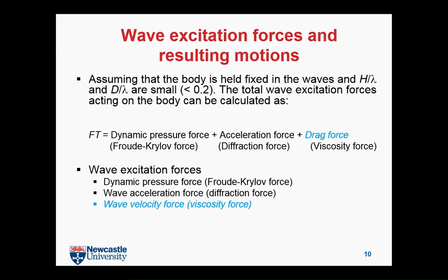One more question regarding this height. When you have a semi-submerged object and you're going to calculate the forces, for the area, do we calculate the height of the submerged part or the total height? Not the total height, because you are doing the interactions between wave and structure, and only a part of your structure is acted on this way. For the force, you're just calculating the submerged part.